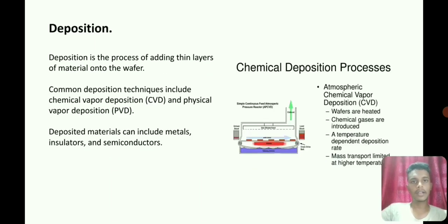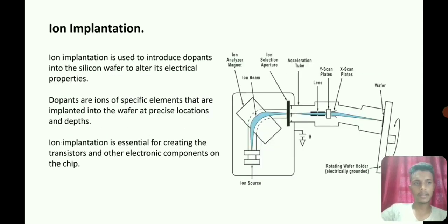And the next, deposition is the process of adding thin layers of materials onto the wafer. Common deposition techniques include chemical vapor deposition (CVD) and physical vapor deposition. It's also called PVD. Deposited materials can include metals, insulators, and semiconductors.